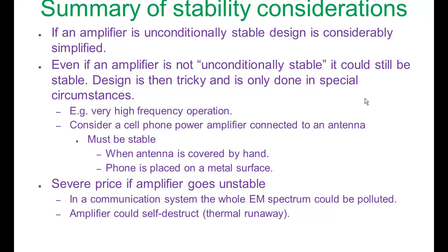We have some issues at lower frequencies, below 5 gigahertz, and at frequencies above 11 gigahertz. But we're not trying to design our amplifier to have good gain there. We don't care if we simply suppress gain altogether. But at 8 gigahertz, our active device will result in unconditional stability.